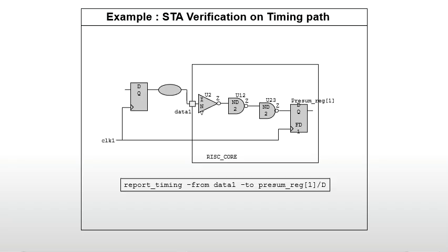In the design shown, the reg-to-reg path begins at the output of the first flip-flop, FD1, triggered by the clock edge. The signal propagates through the intervening combinational logic, passing through the inverter and NAND stages, each contributing its own delay. The arrival time at the input of the second flip-flop, FD2, is then evaluated against the required time window defined by the clock period and setup constraints.